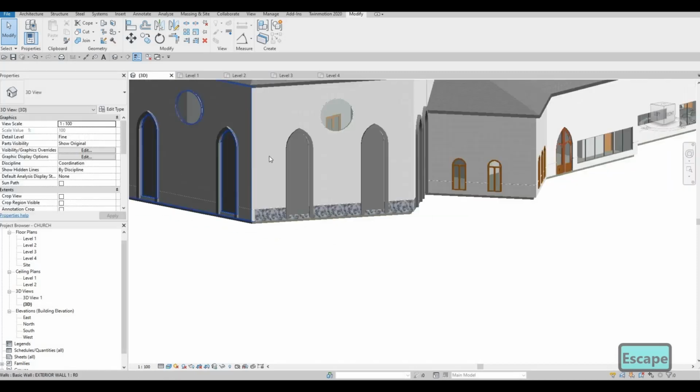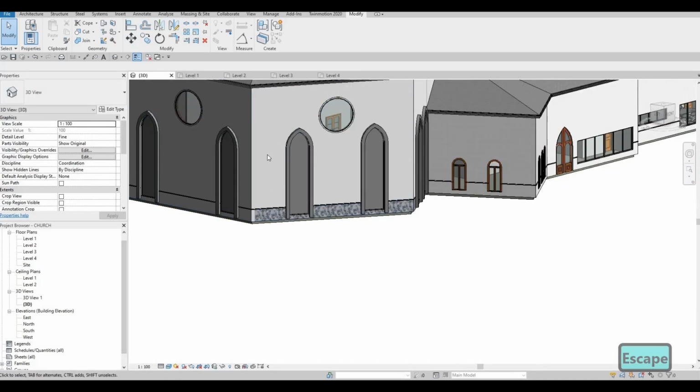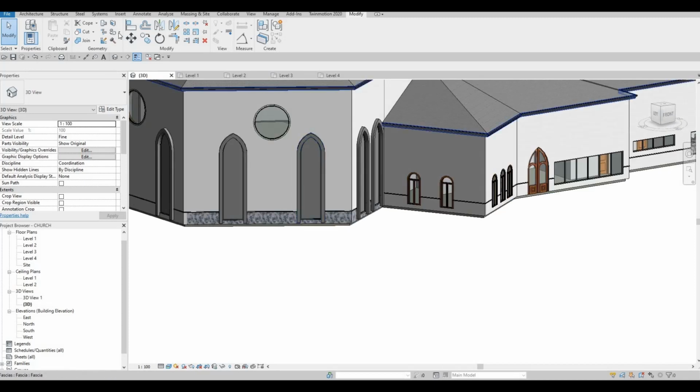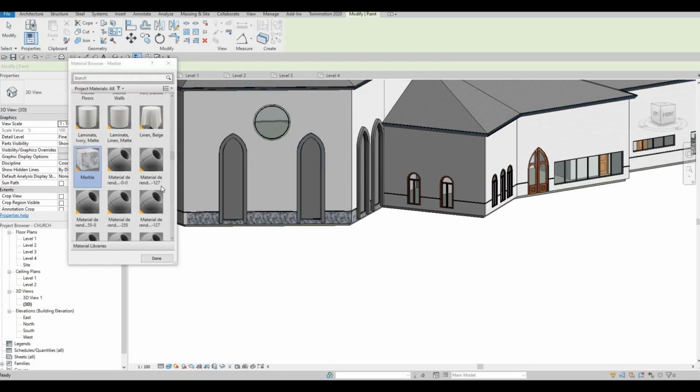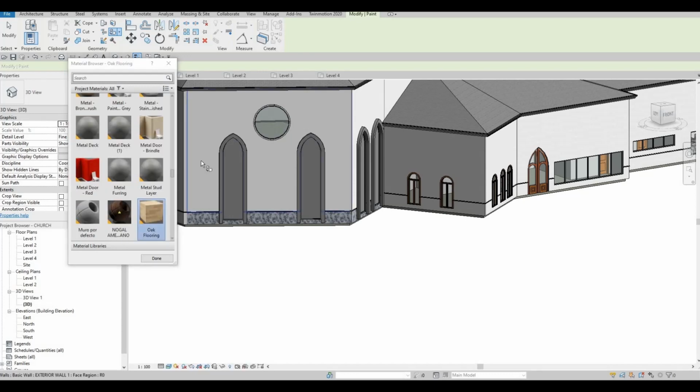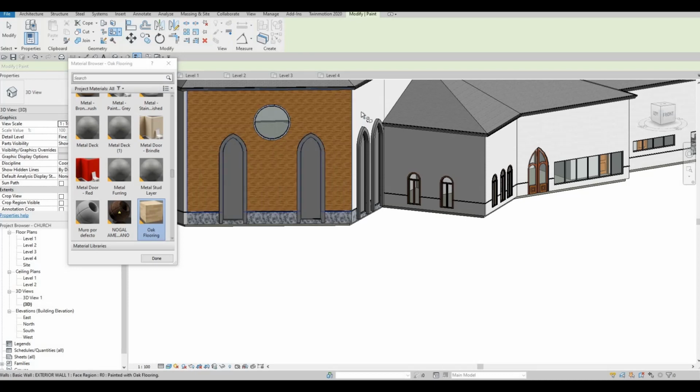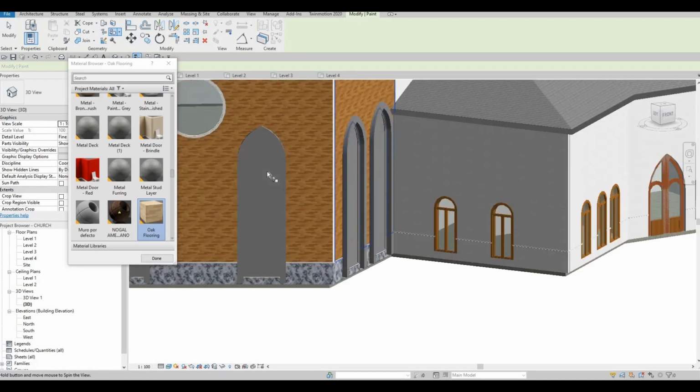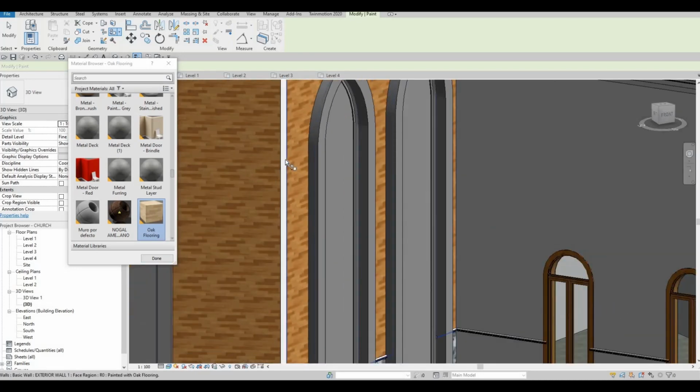So basically we can select the wall above now to a different material. So just for example, I'm going to select that wall and change it to maybe wood, so oak flooring. So now I could select this and split.